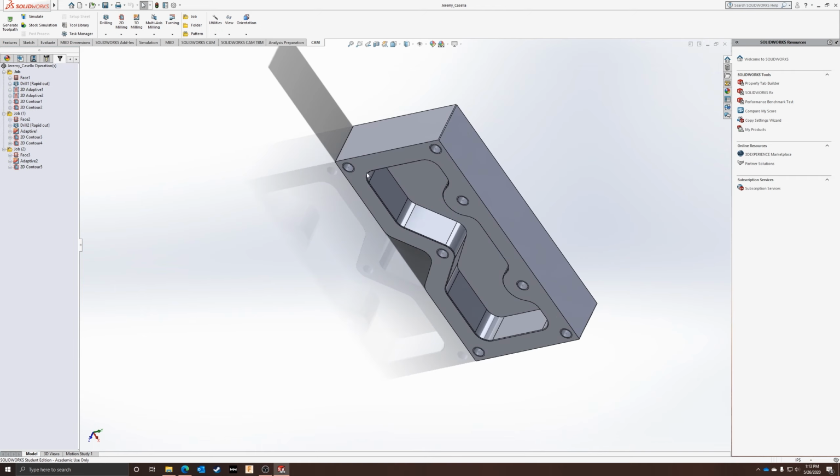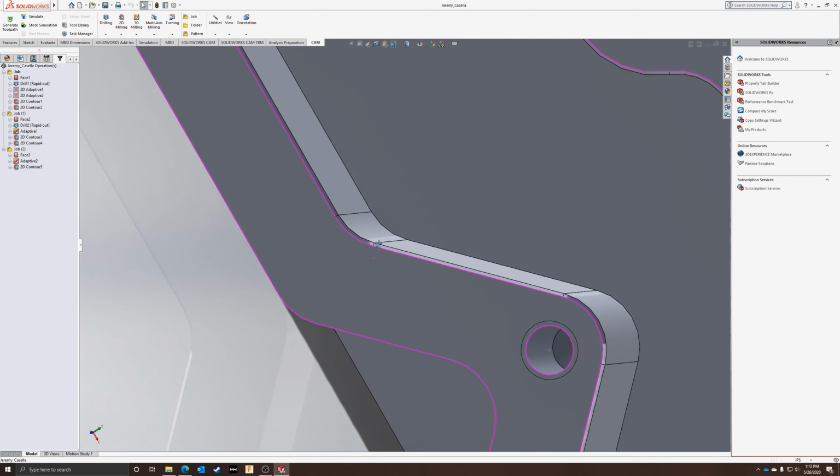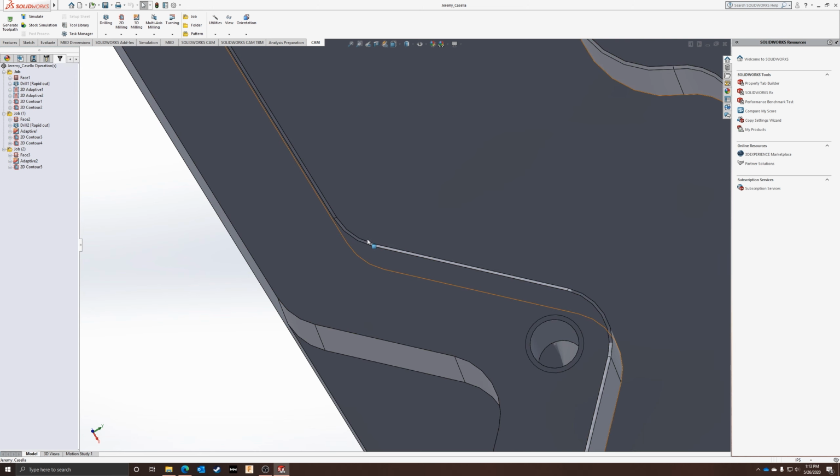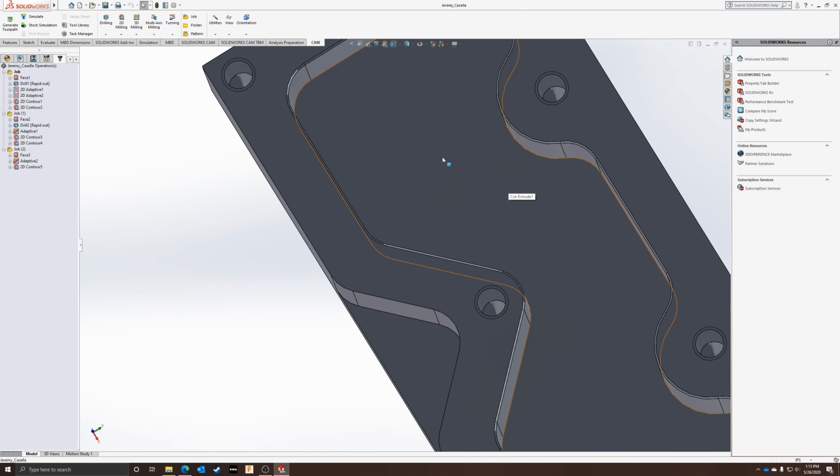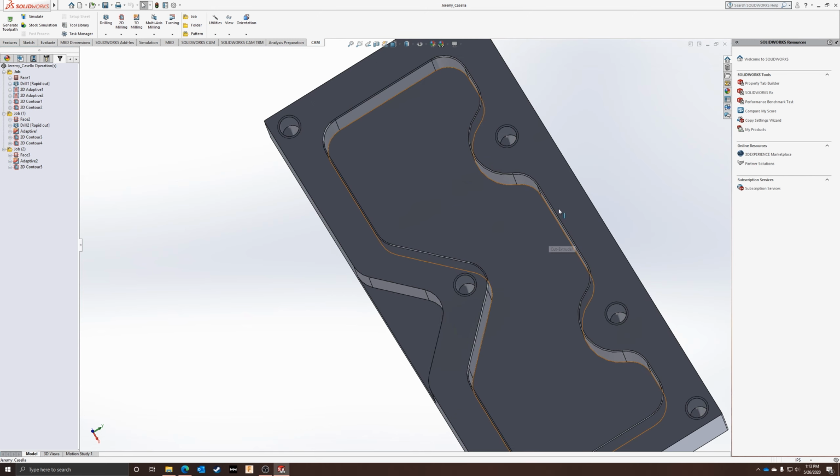If you design a part with a radius that's really, really tiny, that's going to be utterly pointless. If you design a part with a really, really sharp corner, that can't be machined, right? So you got to think about what's happening when I make this part. In our sense, especially, standardize everything to a decently sized number. If I have to drill a hole and it doesn't matter how big that hole is, pick a quarter 20, quarter 28 if the threads are important. But if it does matter, you can make it something custom, right?